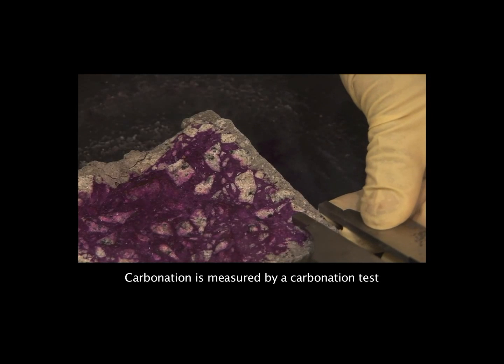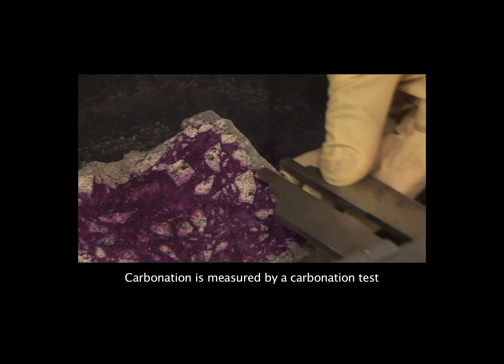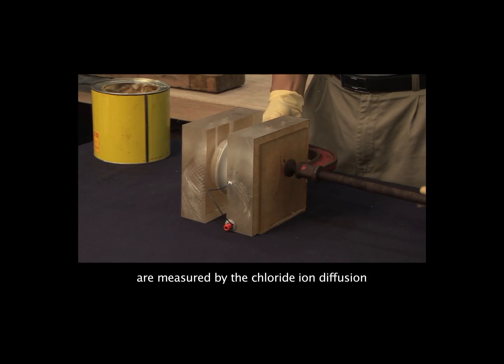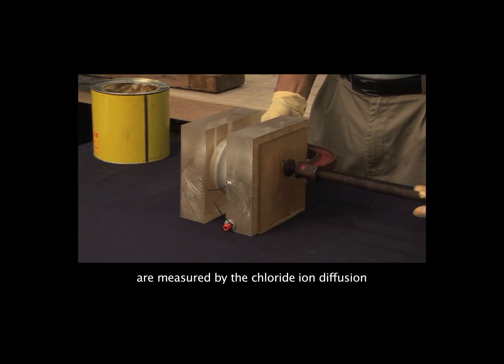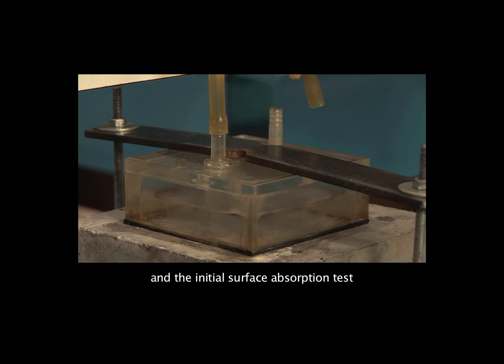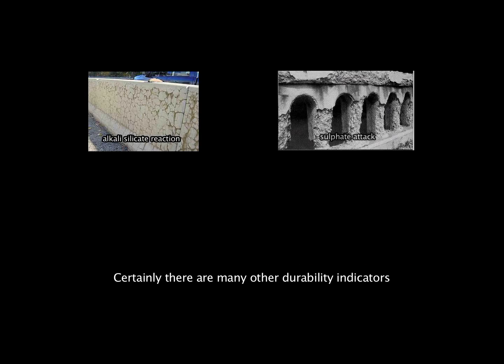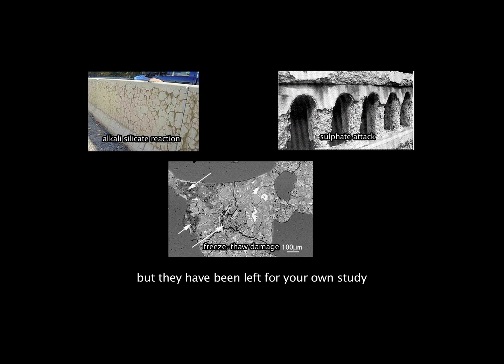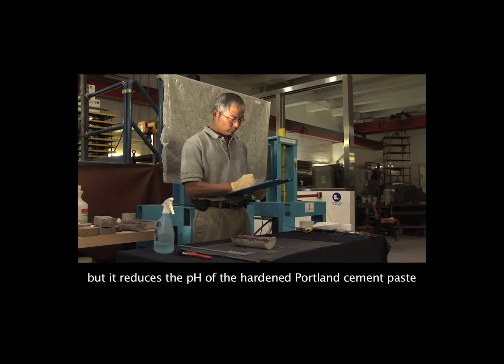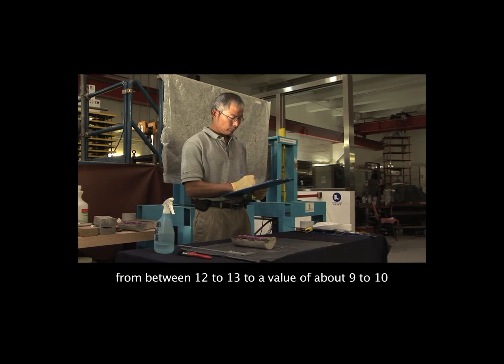Carbonation is measured by a carbonation test. Two durability indicators of resistance to corrosion are measured by the chloride ion diffusion and the initial surface absorption test. Certainly, there are many other durability indicators, but they have been left for your own study. Carbonation in itself does not deteriorate concrete, but it reduces the pH of the hardened Portland cement paste from between 12 to 13 to a value of about 9 to 10.